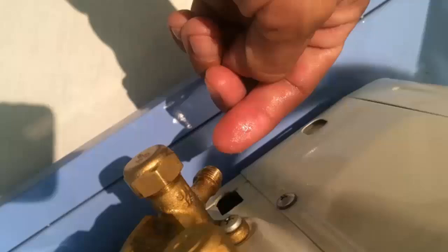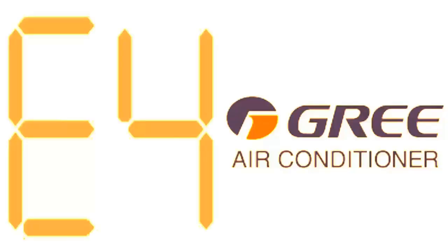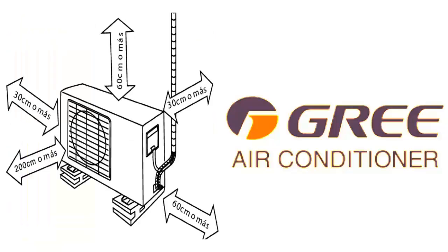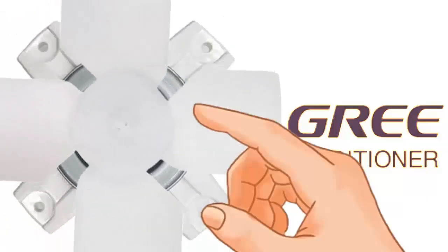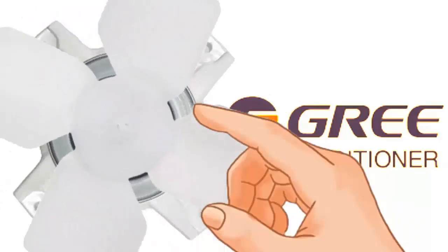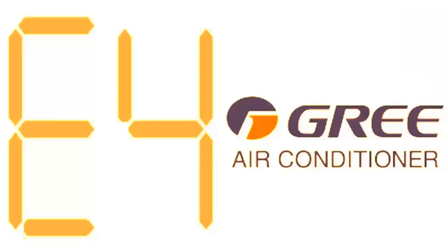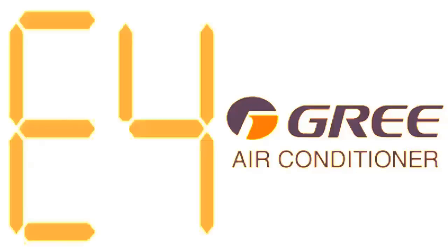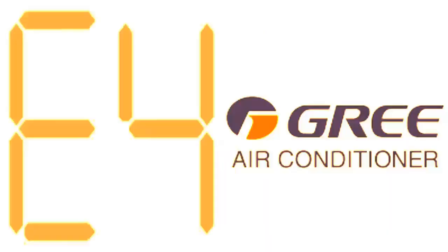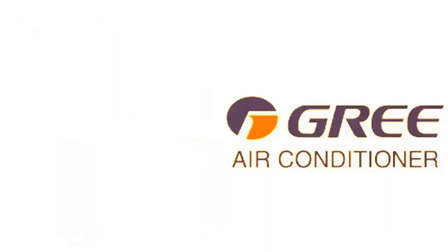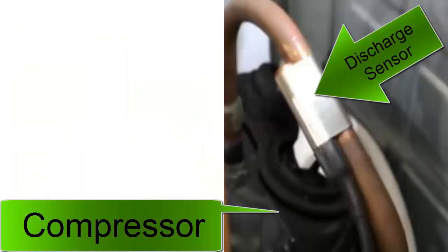A. Check for refrigerant leaks in the same manner mentioned earlier. B. Ensure adequate airflow in the outdoor unit, verify the proper rotation of the outdoor fan, and clean the outdoor coil if necessary. C. Also, verify that the pipes connecting the outdoor and indoor units are properly insulated. D. Finally, test the temperature sensor using the procedure explained at the end of the video.